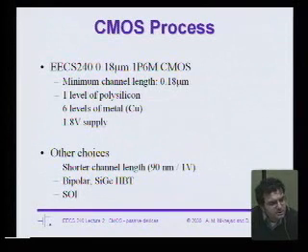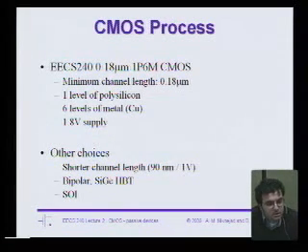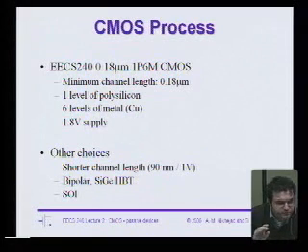The trends have actually changed a little bit. Let's say 10 years ago, the best digital process was more expensive than, let's say, one generation back. But you knew that because of digital scaling, because the whole industry was using that process, within a couple of generations the cost would come down significantly. And so even though there was a small barrier to going into a new fine-line digital CMOS advanced process, you knew that was just a temporary thing.